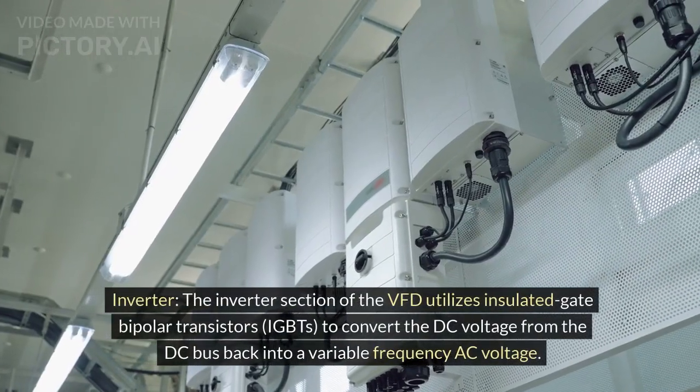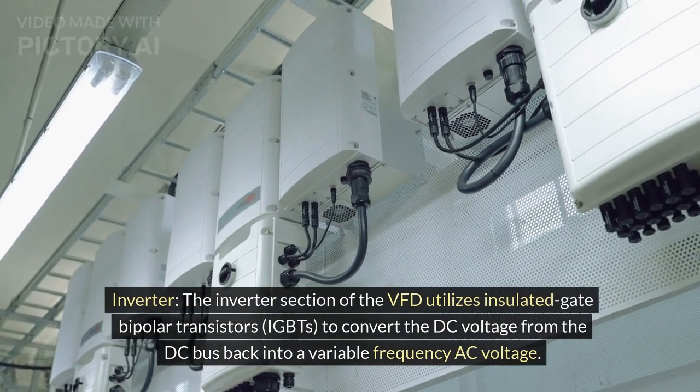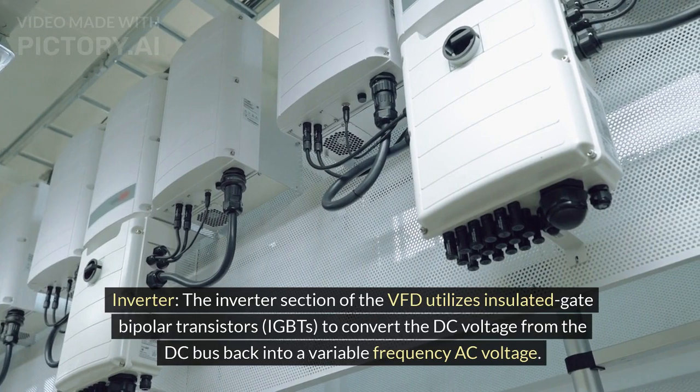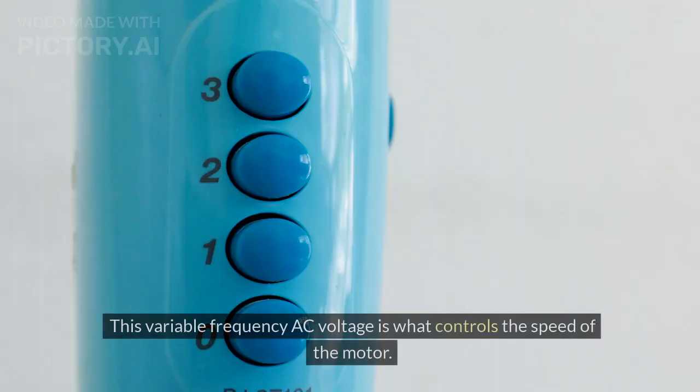Inverter. The inverter section of the VFD utilizes insulated gate bipolar transistors, IGBTs, to convert the DC voltage from the DC bus back into a variable frequency AC voltage. This variable frequency AC voltage is what controls the speed of the motor.